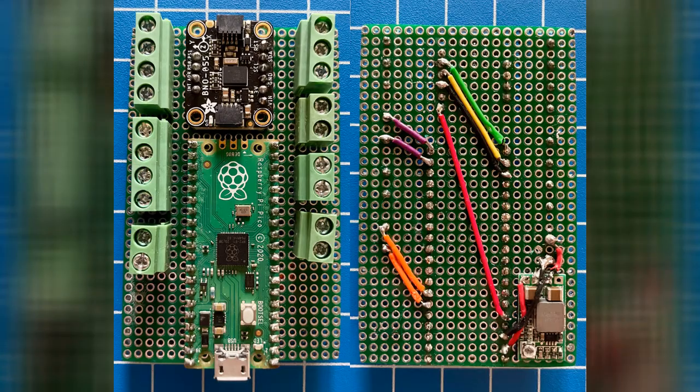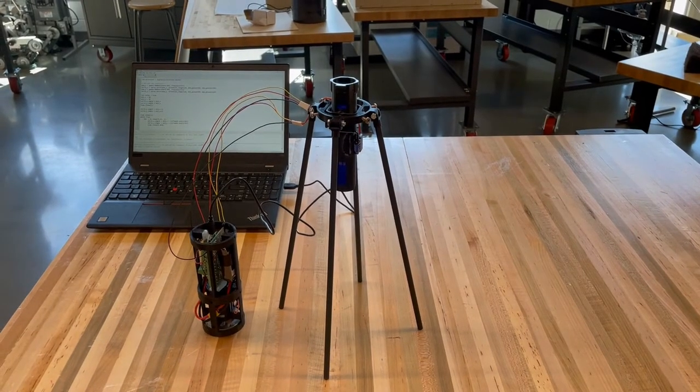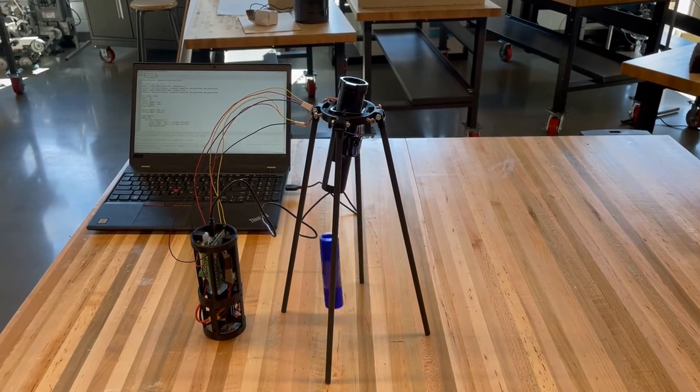Both these control systems connect to a custom flight computer that runs all the flight software on board the rocket. It houses a gyroscope, accelerometer, magnetometer, and altimeter, which all provide orientation and motion data to be used in the next objective. The flight computer is also able to directly interface with the simulation and actuate the control systems in real time as the simulation is running.